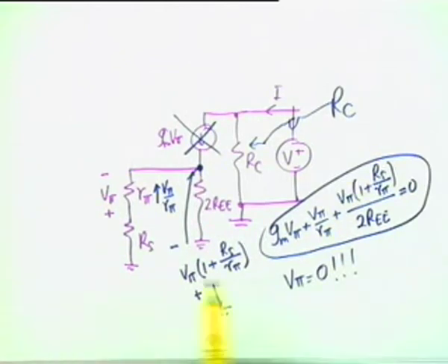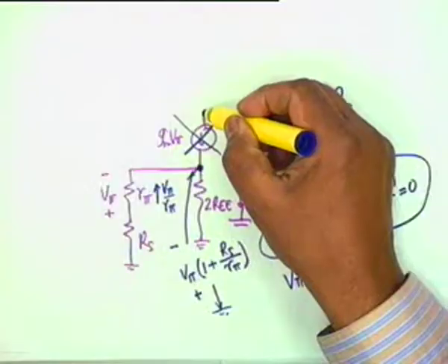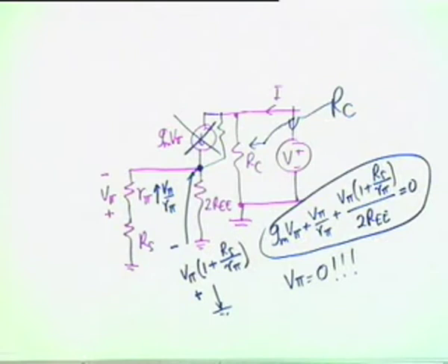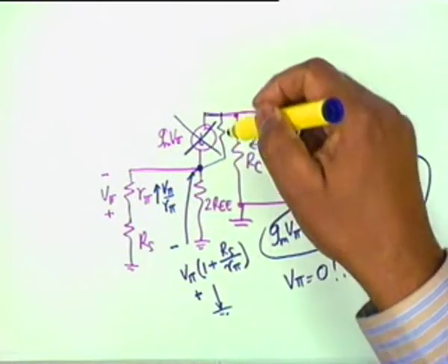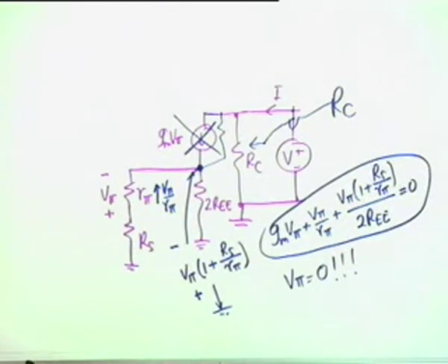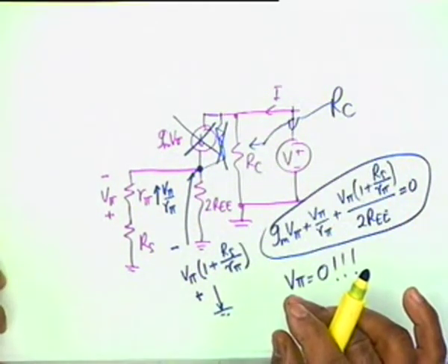So what happens if we consider small r0? Then the situation is quite different. Then you have to have V minus this voltage divided by r0. Therefore, V will come into the picture. If r0 is there, then all this simplification vanishes, and life becomes a little more uncomfortable.